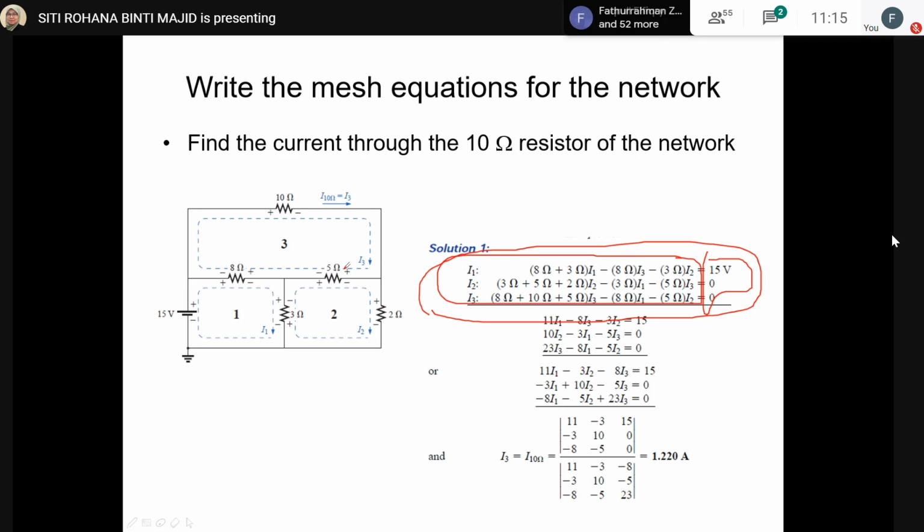So that is the basic concept that you can apply for each element, such as the resistor. You have to label which current goes in and goes out through the element. Then you proceed to create equations for the networks, for each loop.